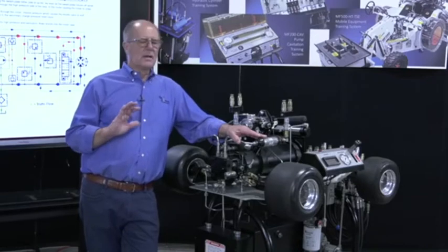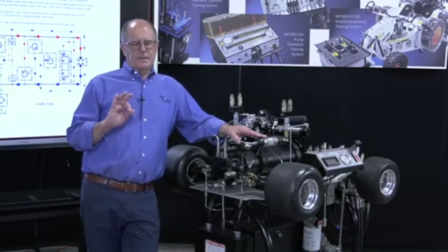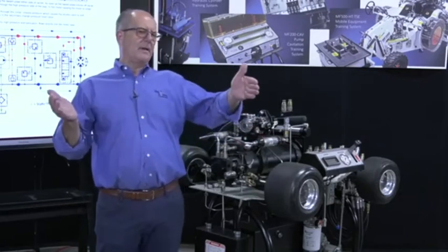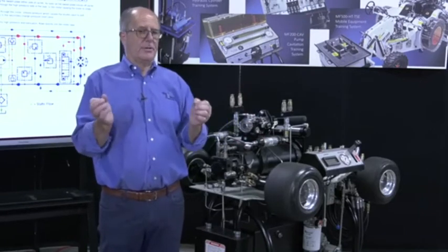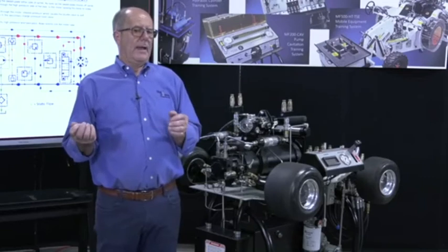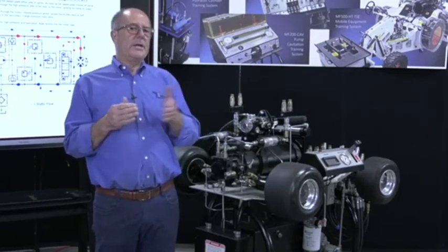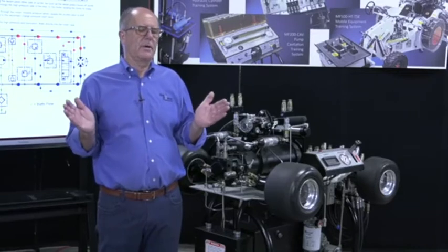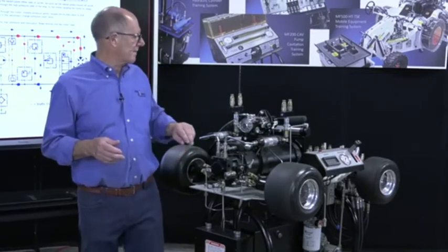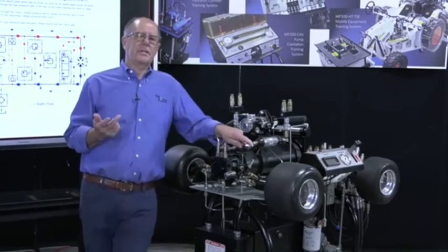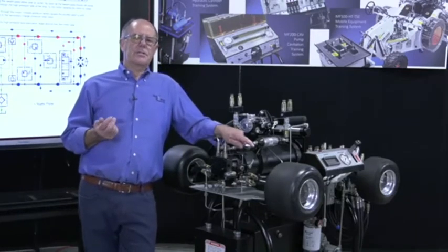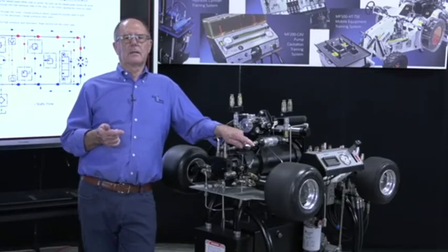So there's that one particular test where they plug the live end port and then they put pressure in the closed end port. And if it's leaking, it'll regen out. That is probably the most dangerous thing you could ever possibly do. The reason why that test is flawed is because if the cylinder has a dual seal system in it, and the seal on the live end is not leaking, it doesn't work.